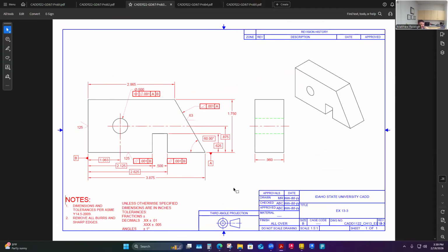This is a thousandth, so I'm just going to put this to ten-thousandths again. And I mean, that might be too coarse, but I'm just going to jump on that side of things rather than be this ultra fine. Just for no real reason, because I don't really know the relationship of the part to something else, but only because I'm erring on the side of maybe a general tolerance versus some really high critical tolerance here that this maybe would apply. So I'm just going to change this to ten-thousandths.